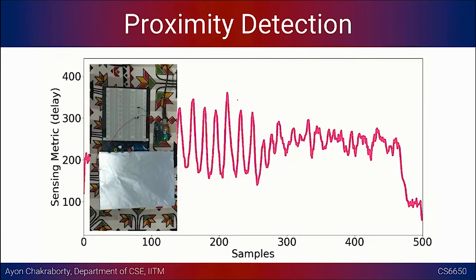Because these are basically time series data that you are getting, you can look at the frequency domain features, you can look at the spectrogram, the way I taught you in the last class, where I was looking at the spectrogram of the IR sensing data or the PPG data. Even this could be converted into a spectrogram, and then you can try to learn that gesture from the spectrogram, and based on the classification of the gesture, you can trigger actuations, like turning on the fan, light, TV, and so on.